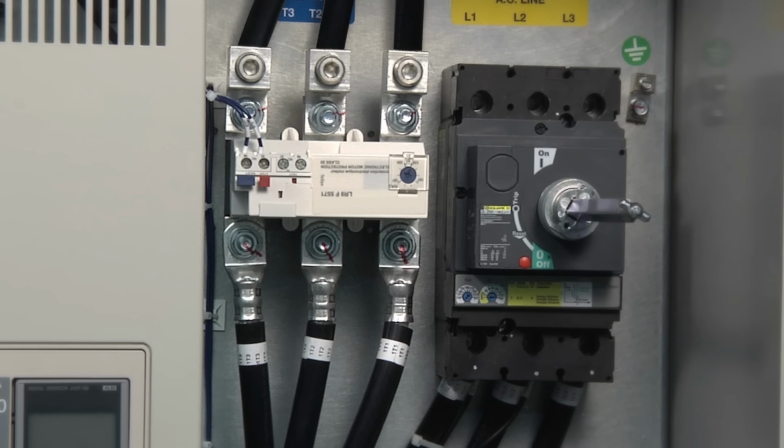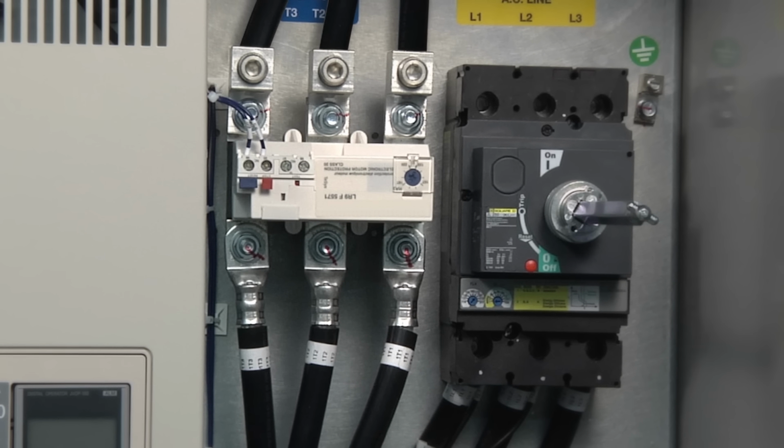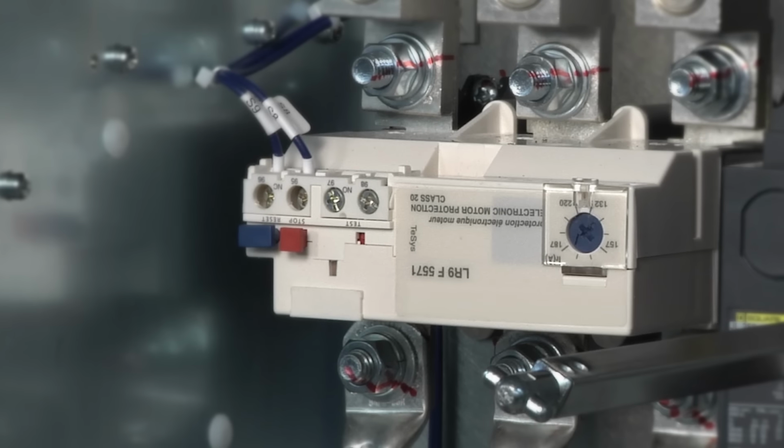The current in the system as a whole is going to increase. When the motor slips beyond its breakdown torque, it begins to produce less torque, which then causes the motor speed to decrease even more and in many cases stall. This situation usually results in damage to the motor if left in this state due to overheating of the stator. Though typically there's an overload relay that will protect the motor from damage.